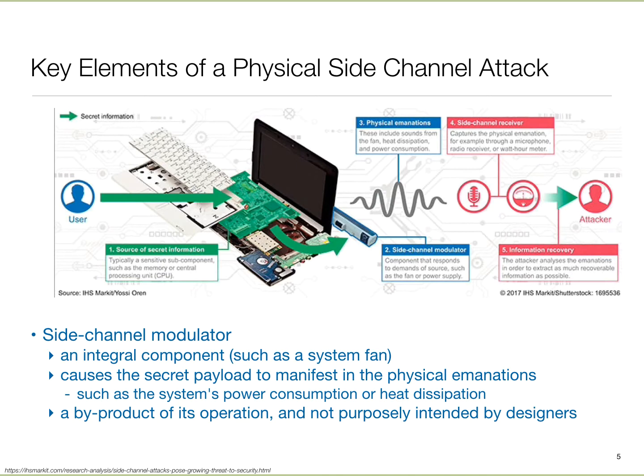If the system is doing relatively little work, we lower the frequency and the voltage in order to save power. Similarly, in order to keep our computers quiet, if the system is emitting less heat, we lower the speed of the fan, and therefore the sound of the fan is a function of the computation that the system is doing.